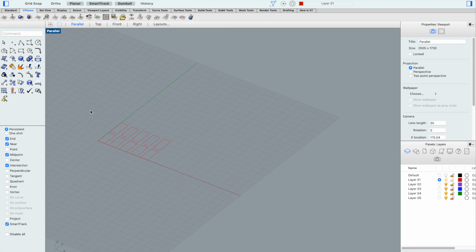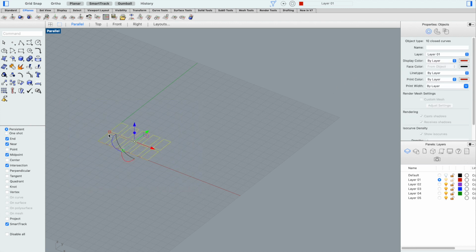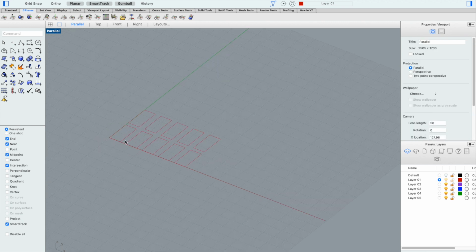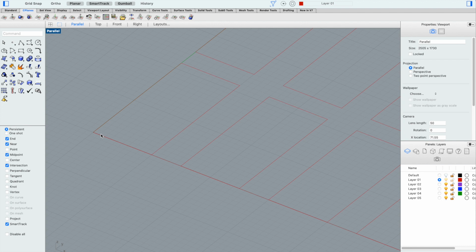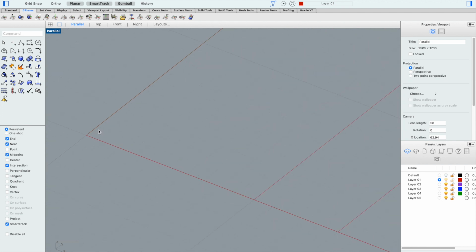Now, let's talk about that for a second because that comes up a lot. In Rhino, the thing that controls the way that you're looking at things is just called the camera. The way that it sometimes misbehaves is that, this happens a lot when you change the scale or if you have a really big file, you might find that it becomes very difficult to zoom in on something all the way. Now, I'm not having that problem because my file is very well behaved right now.